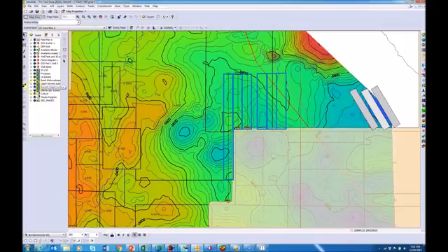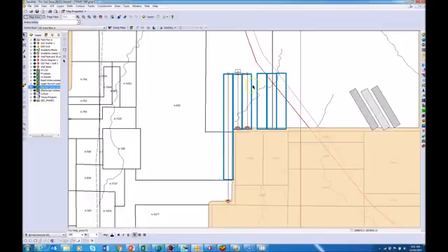And I'll turn off the target surface to better let you see these Wellbore diagrams. Notice that they are stopping at the edge of the lease buffer, but in this case this one is extending beyond the drilling window, but I can simply click on it to select it and move it back manually.